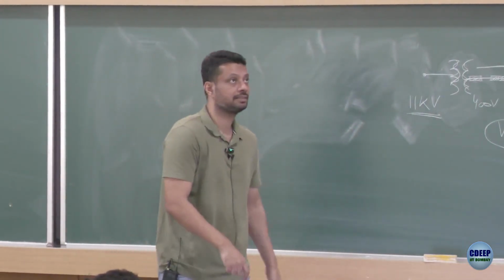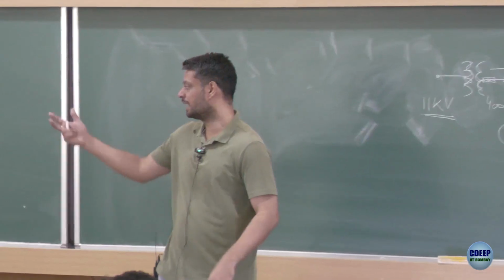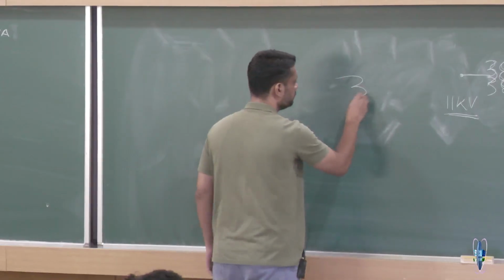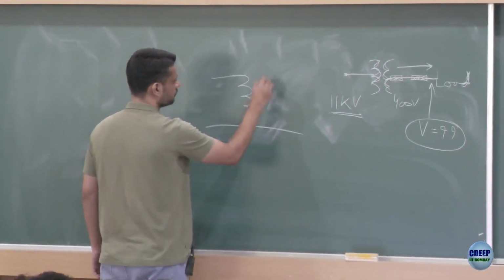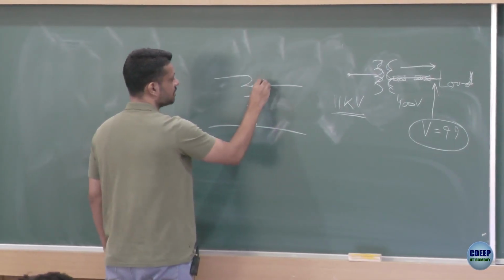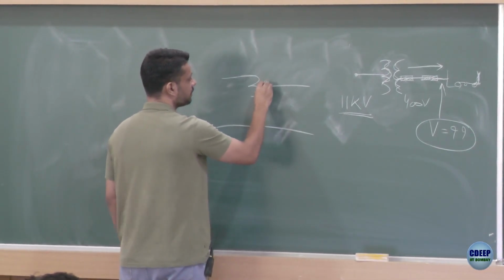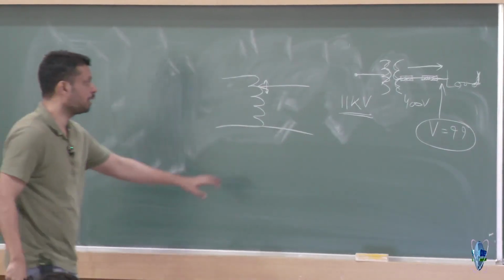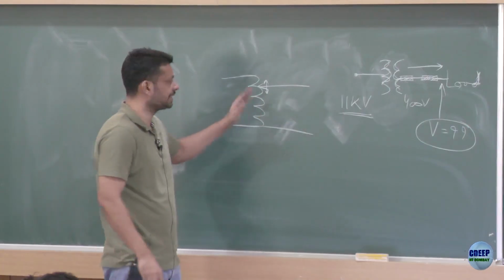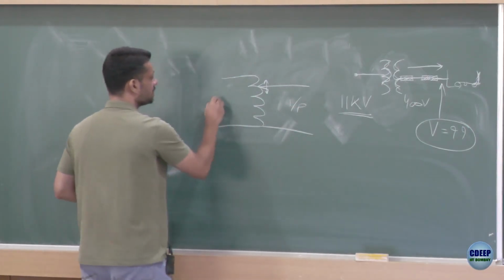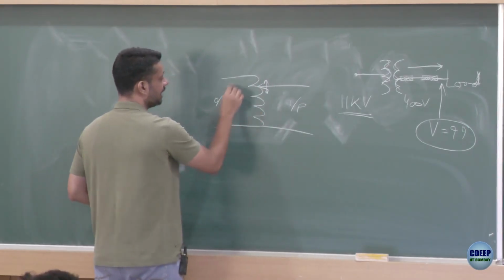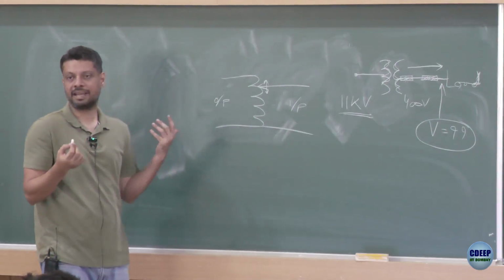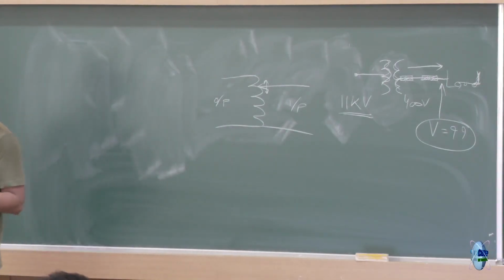So what you can do is, in this room for example, I can connect an auto transformer. As soon as power comes in there, it will go to an auto transformer. And then I can change the number of taps in the auto transformer by rotating that knob, right? And that would adjust my output voltage as compared to the input voltage. In this case, if this is the input voltage to the room, this is the output voltage. So I can get a higher output voltage as compared to the input voltages, right? Is that okay? So basic principle is, yes, you have to use some form of auto transformer.